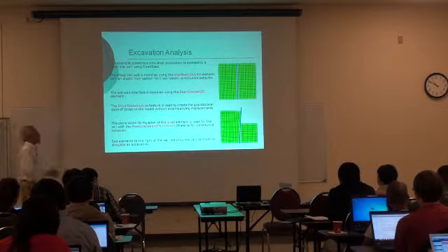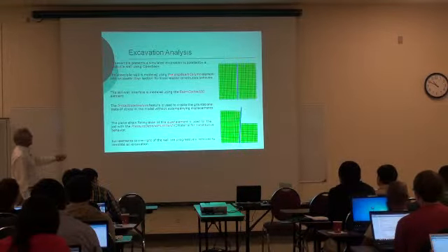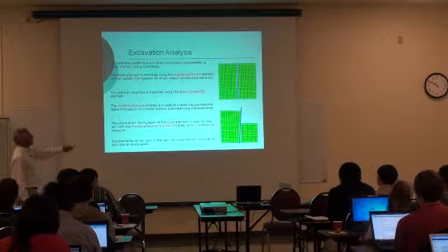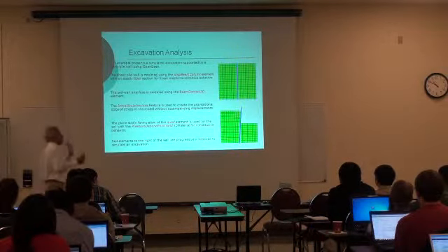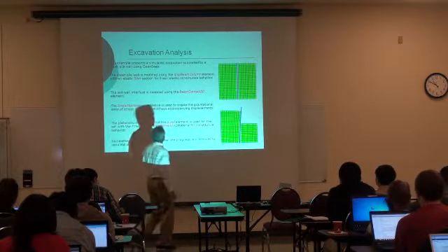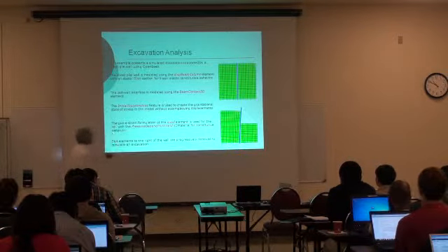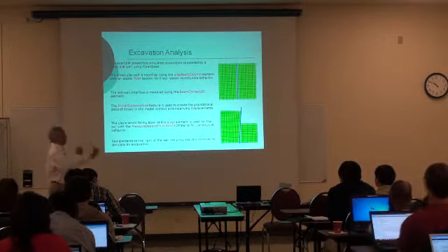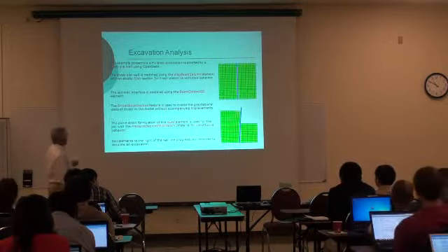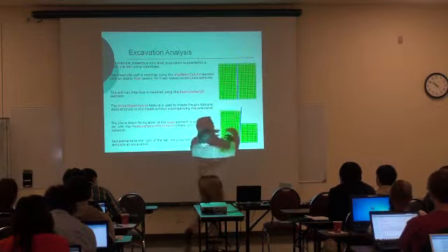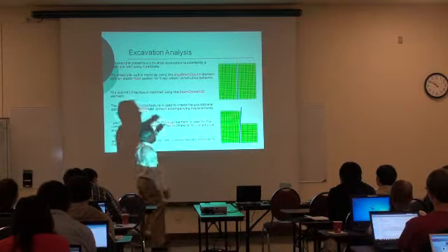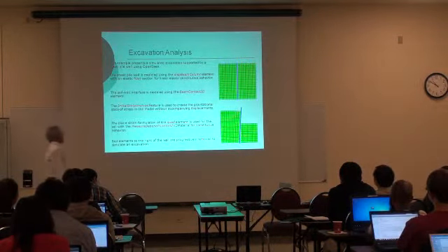It's not that simple. Some codes can do that. Here what we use is the displacement beam column and the fiber section in order to capture the nonlinear response of the wall. Then we use the beam contact two-dimensional in order to capture the interface. We use the initial state of stress command in order to apply gravity and then remove the displacement. That's important to characterize the interface there.